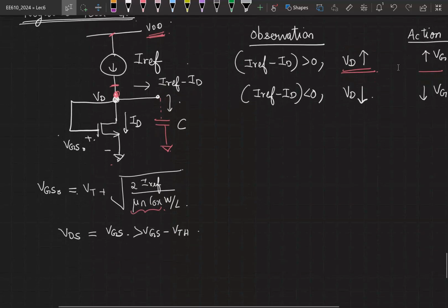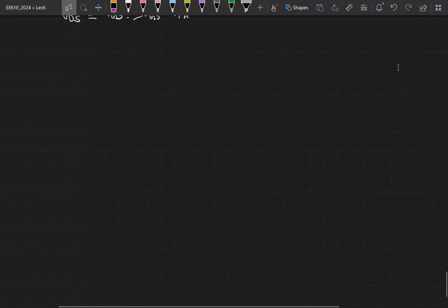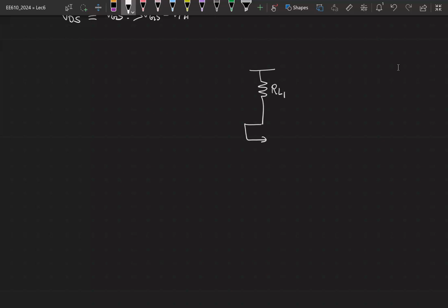So we did all of this so that we could bias our amplifier transistor. Let's say this was the transistor that we had earlier. Initially we set the gate to source voltage using a contraption like this, where the gate to source voltage was maintained as a constant. Now I want to replace this with a battery that is able to track any variations in VTH.